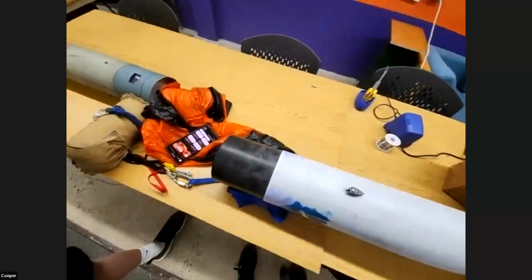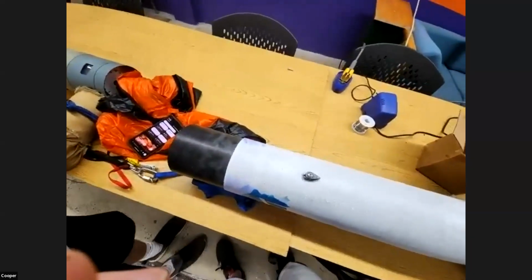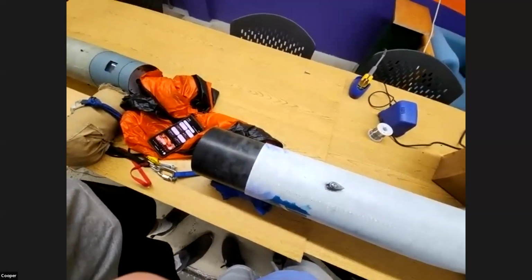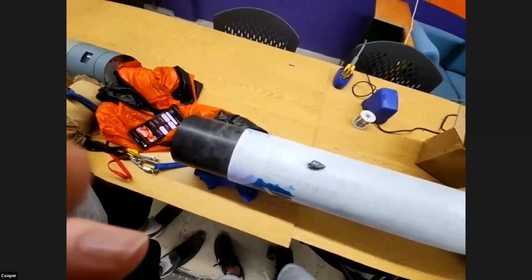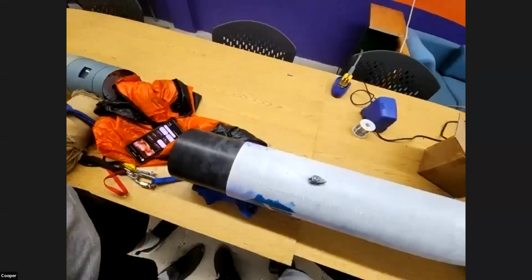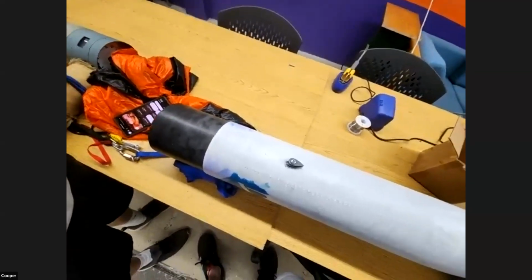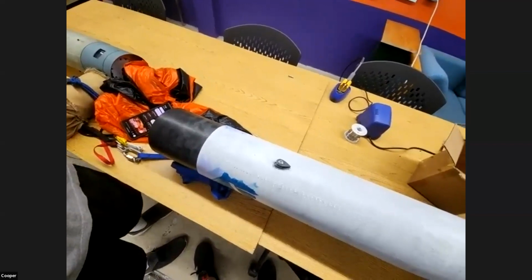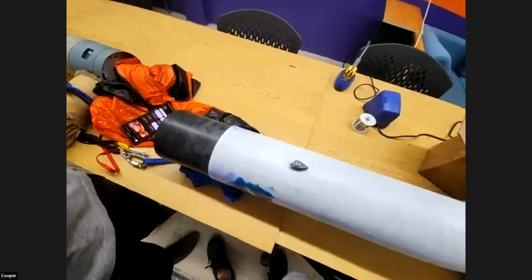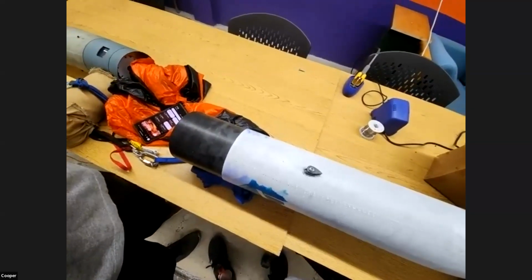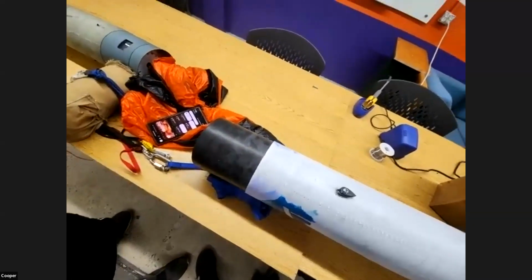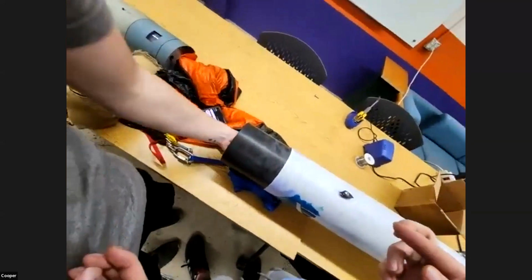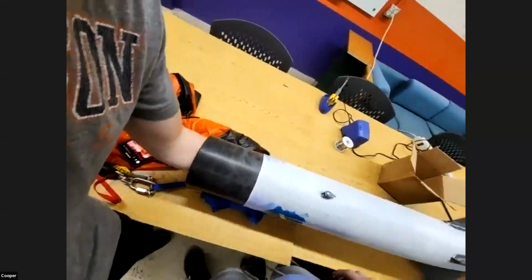Okay, that shouldn't be too hard, from that standpoint. And also the other piece is just make sure that inside the body tube, you don't have a half inch or even a quarter inch of excess threaded nut sticking down, because you don't want anything that sharp and metallic that could be snagging shock cords, cutting shock cords, or ripping parachutes or anything else like that. Yeah, we were planning on grinding down the nut. Perfect. Good deal.